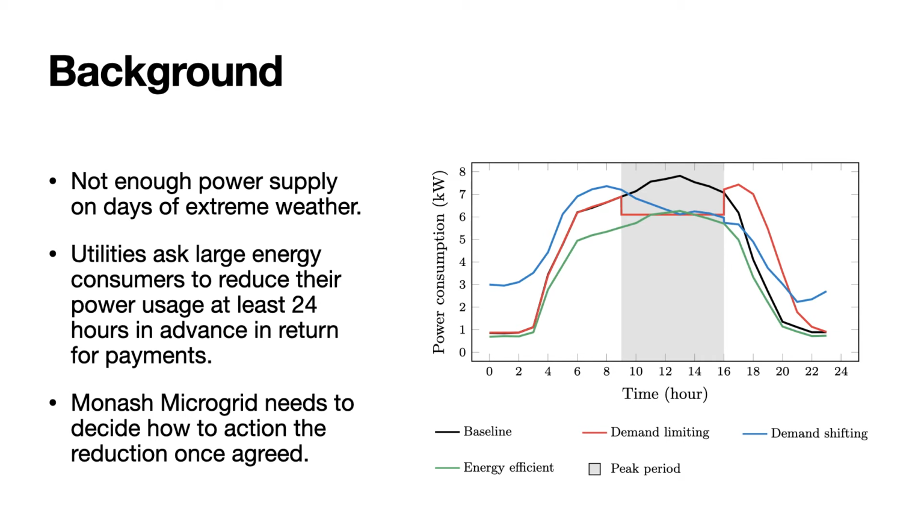We want to shift power usage to earlier in the day when it is not as hot, so we have enough power to run essential appliances during the peak. For example, air conditioning can be turned on earlier to pre-cool the building and let it rise in temperature during the peak. The ultimate aim is to get to the green line. After upgrading some appliances, we don't need to consider this issue at all, but that is much farther into the future.